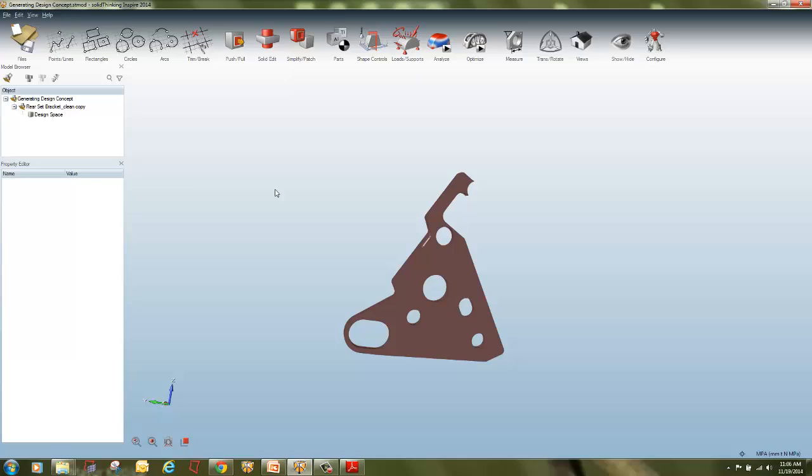Then let's move to the next topic, that is view controls. The view controls are located on the left corner. Here you can see the view controls of the application workspace. While you can use the mouse to adjust the view, the view controls can be used to rotate the model view using the view rotor, fit all or selected objects in the modeling view, switch between perspective and orthographic projection, and rotate the camera to the closest principal axis. We will see one by one.